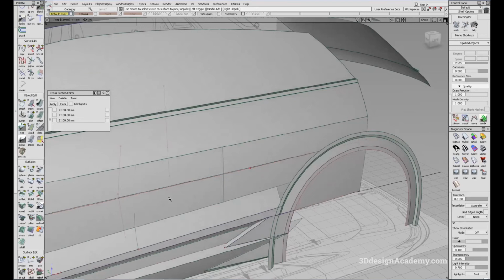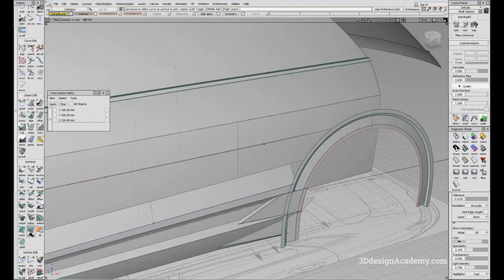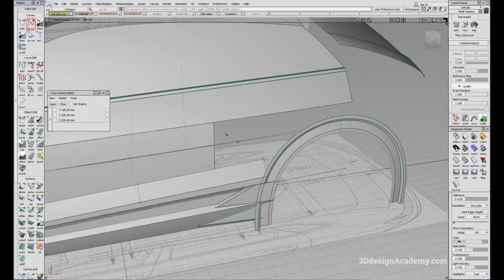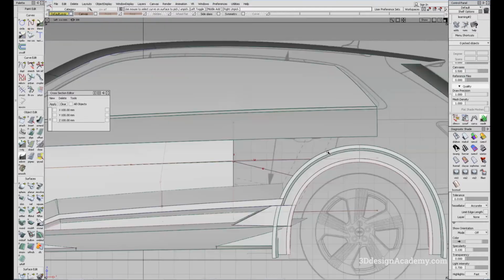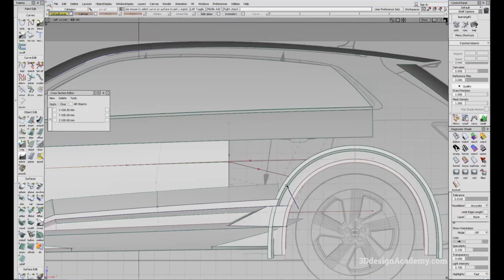and I'm going to actually let me just delete these curved surfaces because we no longer need them, at least for now. So I'm just going to draw trim. And what I'm going to do is create a curve from here to here. I'm just going to make that into degree 2. And let's see, we want to follow this shape as much as possible. So it looks like the core of the fillet is running here to here.